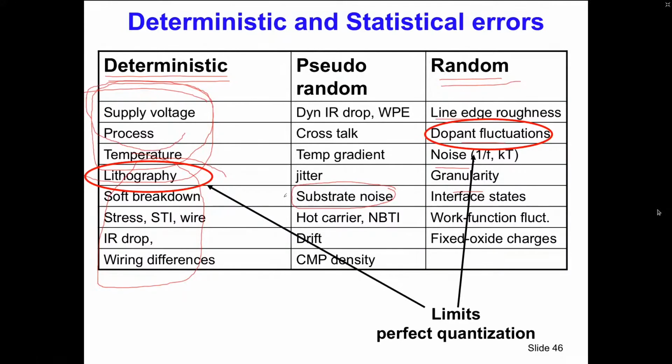But if you have 6 or 8 receiver chains on your chip, on your SOIC, and you have an ARM9 processor there stampeding around, then basically you have to model it as substrate noise. And that's basically pseudo-random stuff.